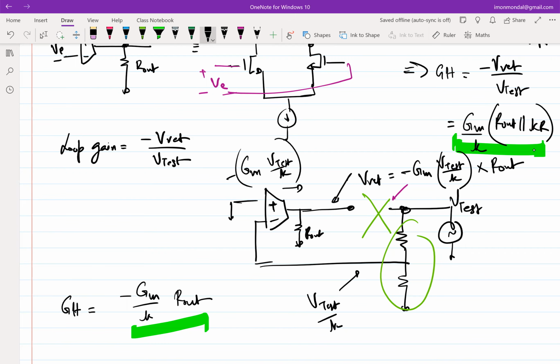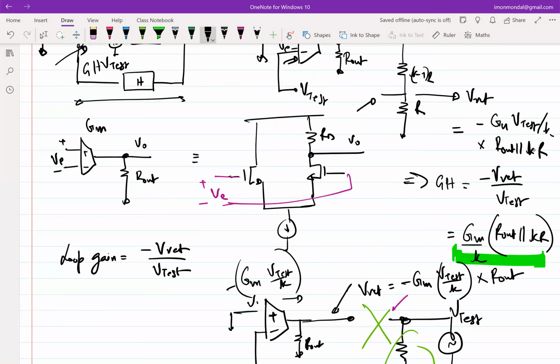Okay. What is the loading effect in this? We expand this differential amplifier. No, you don't even have to expand the differential amplifier, right? The symbol, what is the input of the symbol? Let me call this V1, this is V2. So looking into V1 or looking into V2, you have infinite impedance, right?